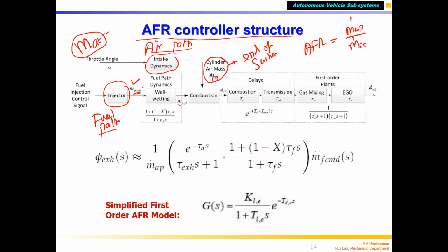This is the fuel injected, commanded. I told you 1 mg, correct? 1 mg of fuel is being injected, and based on this equation, this is called tau. So you can see that this is nothing but tau f. Tau f is the time constant of fuel evaporation rate. Of all the fuel you inject, 1 milligram, 0.1 milligram was sticking to the valve wetting. But the fuel is evaporating as the air is going. So how much fuel will be evaporated can be calculated using this equation.